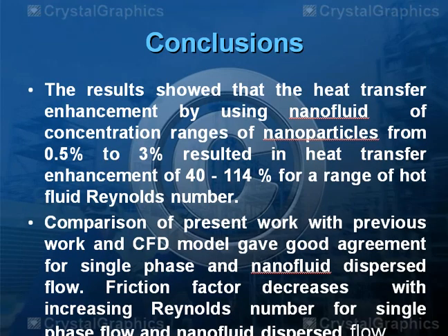The results showed that heat transfer enhancement by using nanofluid with a concentration range of nanoparticles from 0.5 gram per liter results in heat transfer enhancement of 40 to 114% for various Reynolds numbers. Comparison between the CFD and present work, both with nanofluid and without nanofluid, shows good agreement.